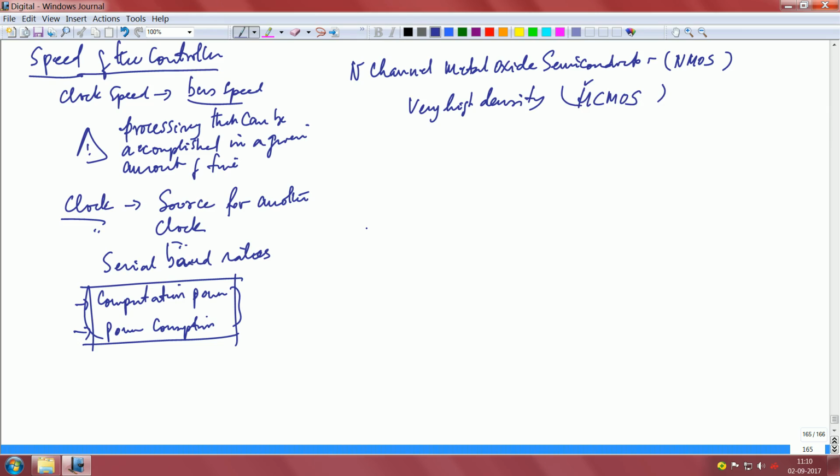The advantage of this is that it can drive signals from rail to rail, unlike earlier CMOS processors. Hence this criterion can significantly affect the design. Because of its ability to drive rail to rail, noise issues in system design should be borne in mind. HCMOS uses